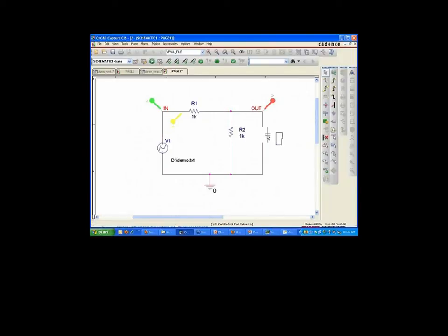It's actually not going to let me, for exactly the same reason. I can't put that component back into there because I'm making netlist level changes. I'm changing what that cap is connected to by moving it in there. There are tricks to get around that, but the feature is located right here in the icon. You can hit drag connected objects. That's the little icon. I'm going to toggle that button, and that puts me back to pre-15.7 behavior.